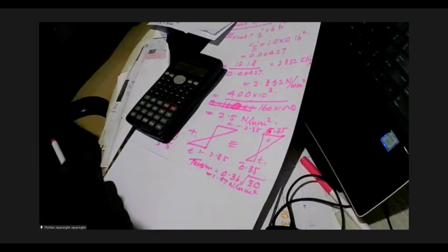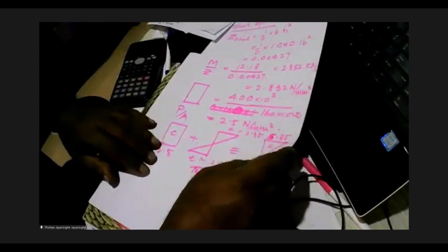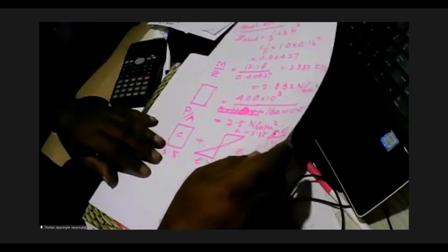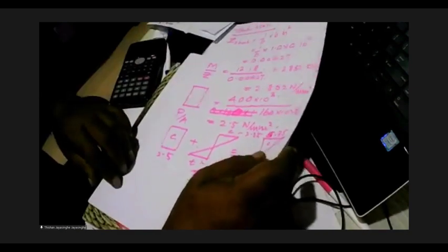So you can make use of 30 megapascal concrete. But if you want a higher durability, you can go for even 37 megapascal concrete. So then we look at the longest span.